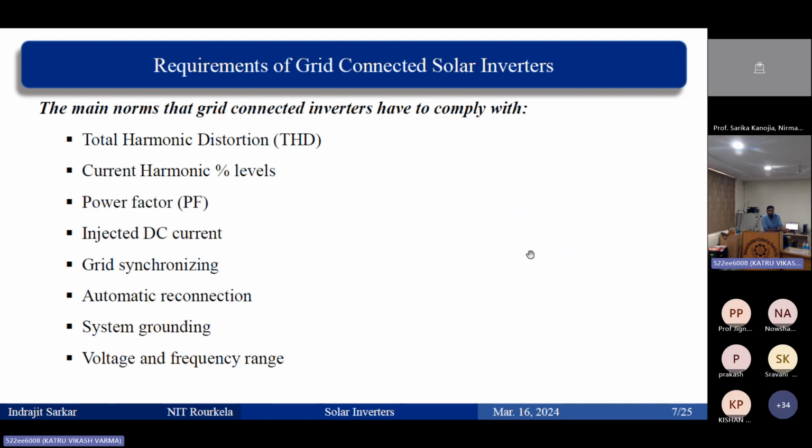If it is a square wave inverter, you will have a number of lower order odd harmonics that are going to be injected into the grid if it is current you are injecting. And if it is a PWM inverter, then you are going to inject high frequency current to the grid, right? I am not talking about GaN devices, where the switching frequency may be more than 100 kilohertz. But when it is a PWM inverter with a certain filter,